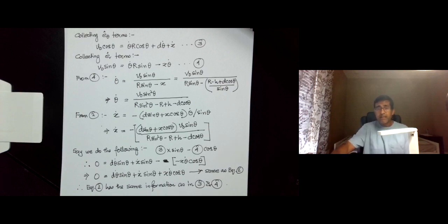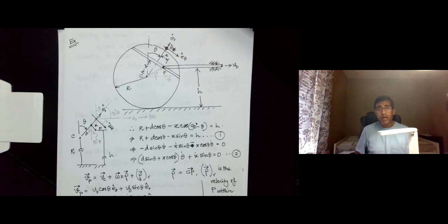So that completes this problem, and what we have seen is a problem on, again, rigid body kinematics. You have a constrained motion in play here, and in addition you have a rigid body kinematics which uses the 3-term velocity expression, Vc, omega cross rho, and rho dot r.